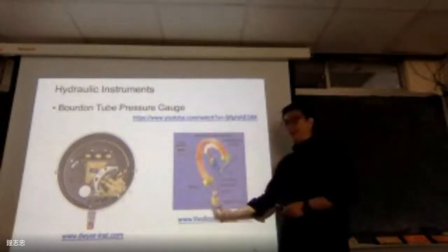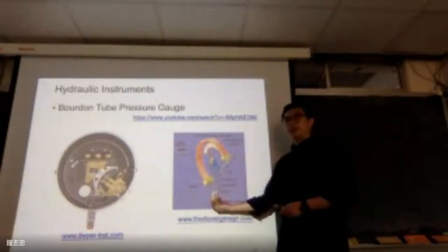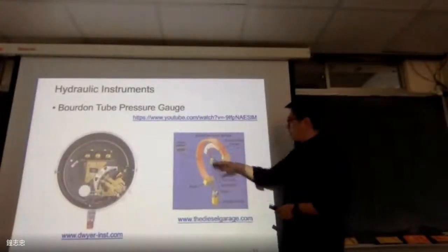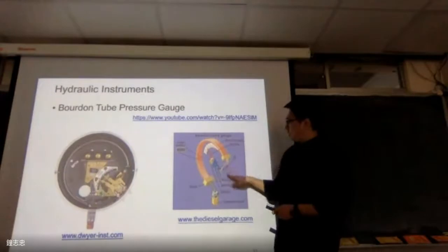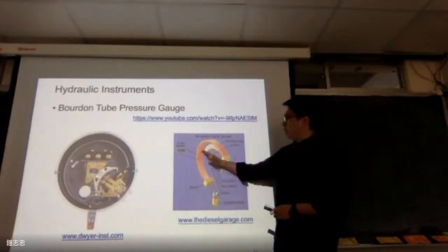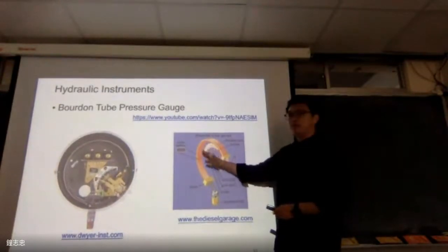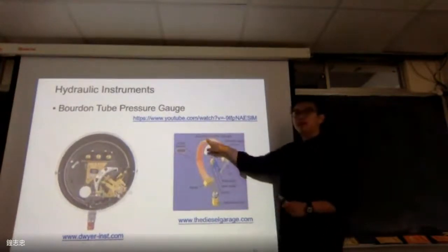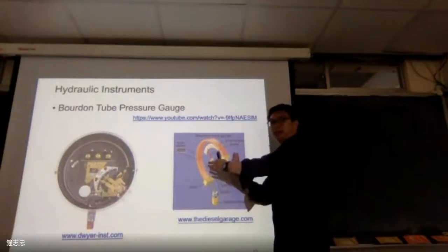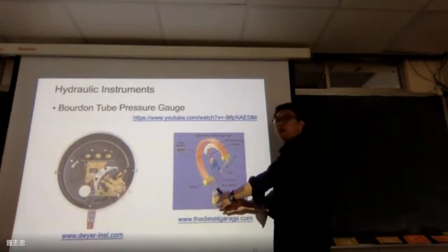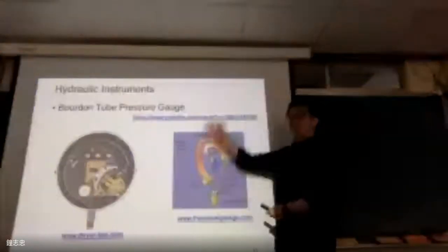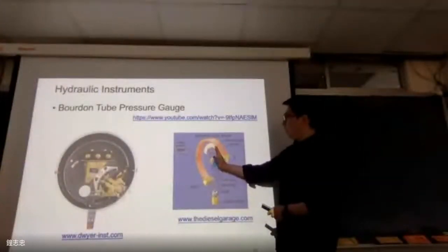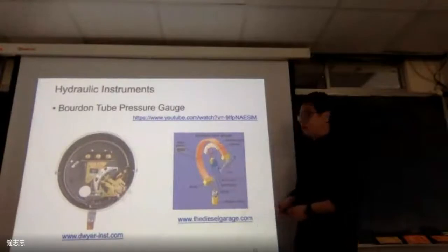I have an inlet of pressure from maybe air or liquid, and with this Bourdon tube you can find the corresponding ticks, so we can know how much the pressure is so far. But of course, you need to calibrate the response and the pressure using the rating curve. That is how we can understand what level of pressure we have.